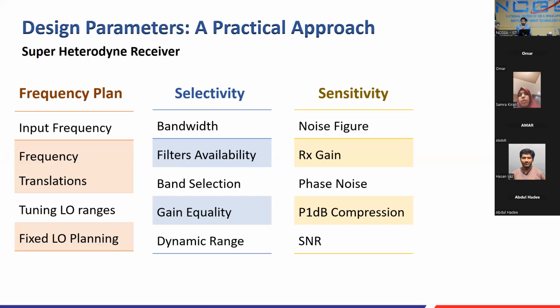Then the next is the P1 dB compression point. It's a very famous term in our microwave circuits and systems, derived usually from amplifiers, where your system acts linearly. When you are increasing the input power, your output power increases. After some point, you will notice that as you're increasing the input power, the output power is not increasing that much. It may be increasing, but you have increased input power by 2 dBm and output power increases by 1 dBm. That is actually the 1 dB compression point, where your gain has compressed by 1 dB. After that point, there is a 3 dB compression point, then there is saturation. So you need to think of the system as linear before that 1 dB compression point, because the effect of the 1 dB compression point is that after it, the harmonics increase.